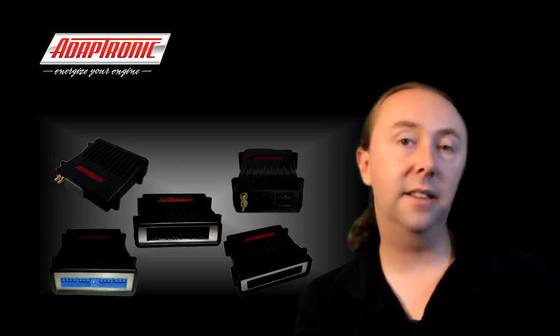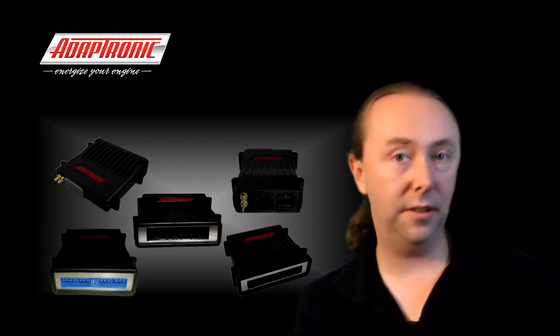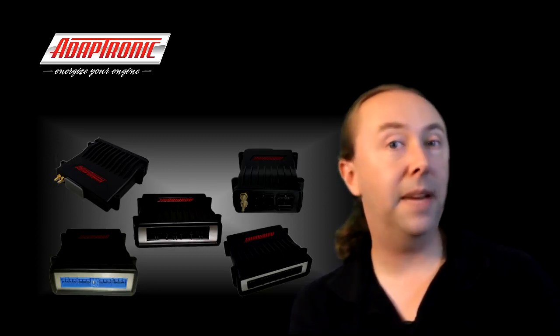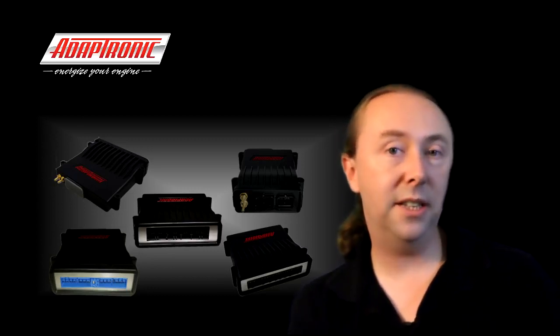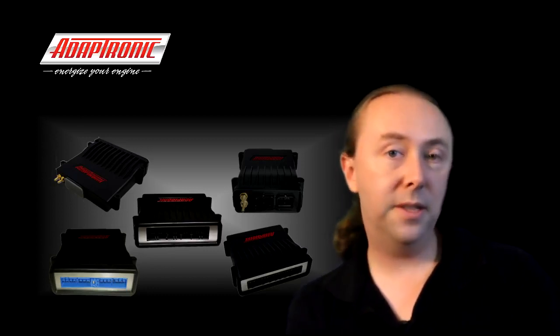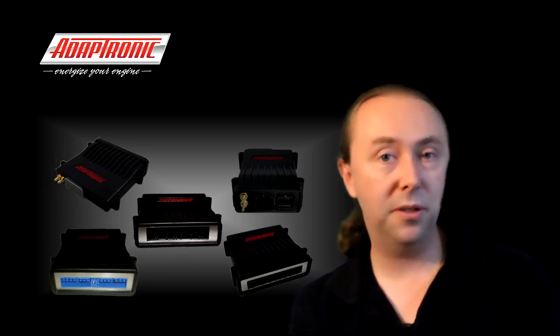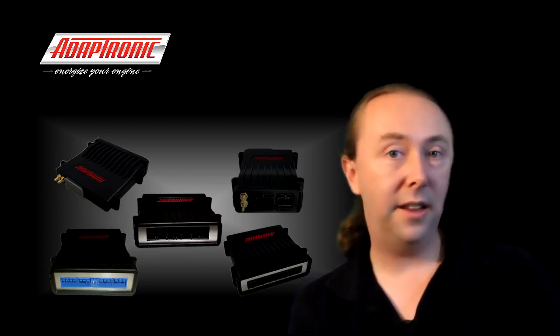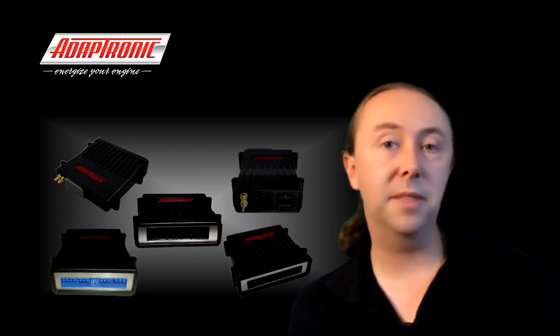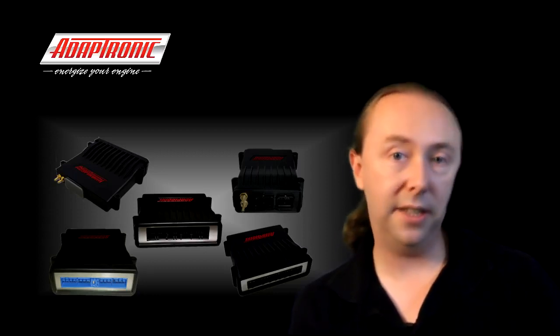Now the fuel injector is designed so that the fuel pressure actually holds the injector closed. So the injector contains an electromagnet, or solenoid, which pulls the injector open against the fuel pressure. Now the force that the solenoid exerts is proportional to the amount of current through the solenoid, and therefore you need a certain amount of current to overcome a certain amount of fuel pressure to allow the injector to open.